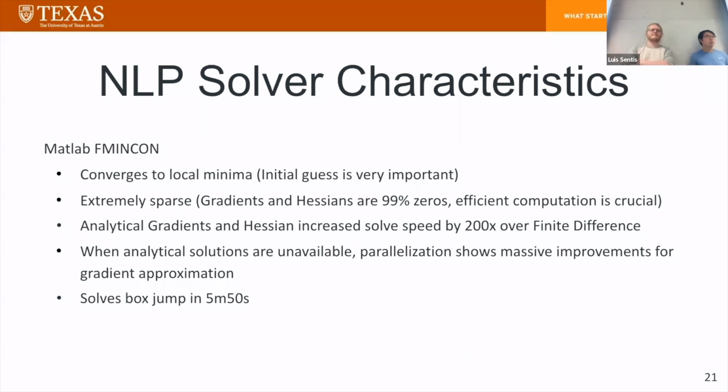You solve it for 5 minutes. So you solve it for the entire jump trajectory. Mm-hmm. But you talked before that you solve it in chunks of 100 milliseconds. I didn't understand. So it's not that we solve the chunks of 100 milliseconds. It's that the knot points are spaced by 100 milliseconds. Okay. Yeah. There are a couple times that we solve it in chunks. 5 minutes was the total. So I think that one we solved a 3-minute chunk without angular momentum and then a 2-minute chunk with it. And that depends. It's really highly variable on the initial conditions and the trajectories and the references. That's running on my desktop computer.